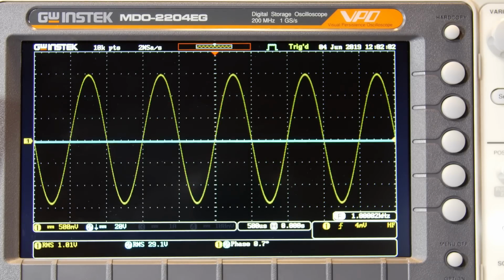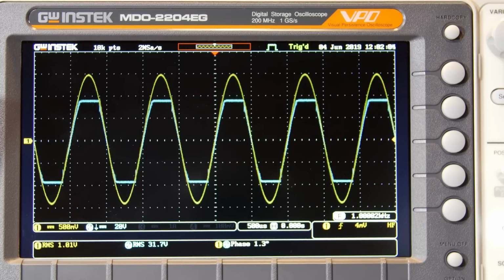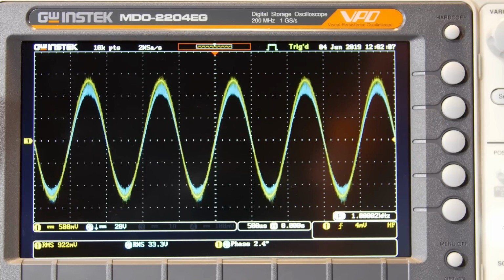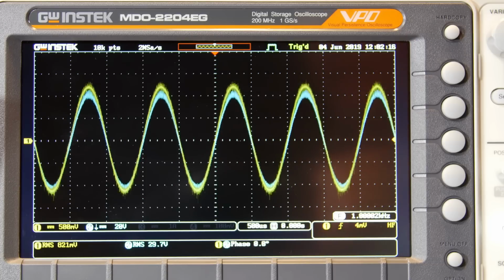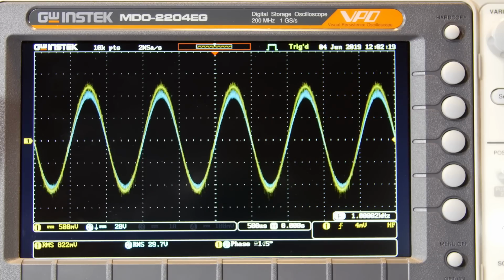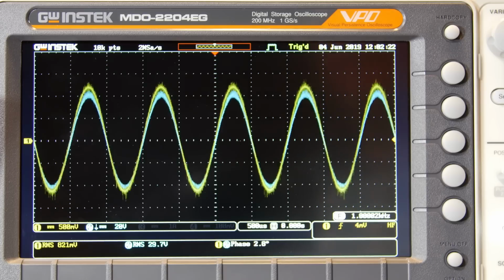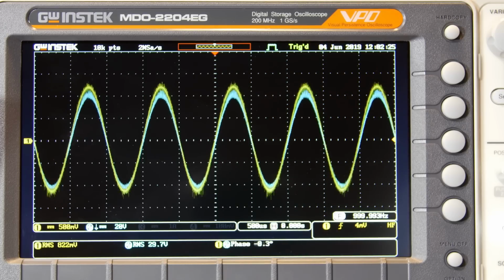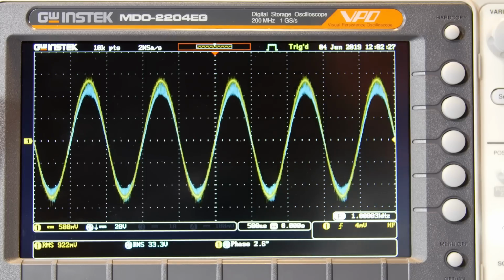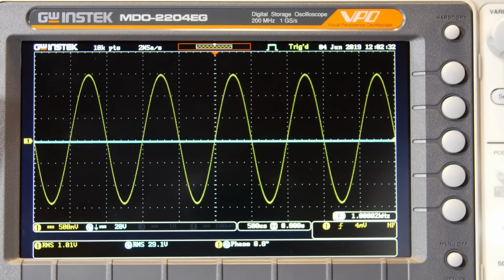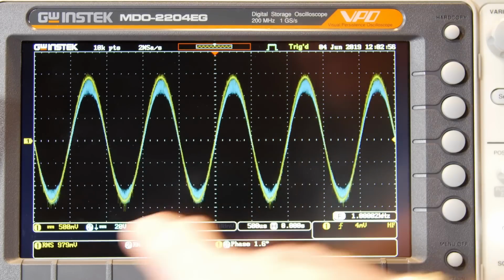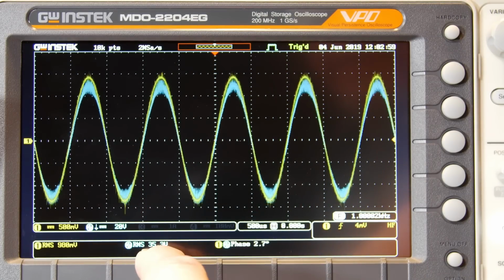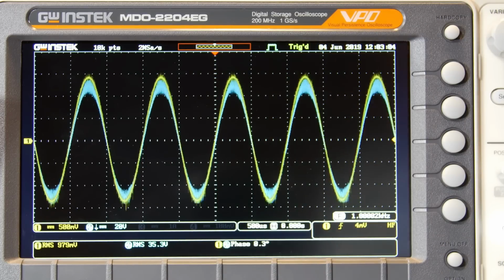Okay, we're right about 3 amps on my lab power supply. It's just tripping the current limit, so that's kind of what happens. Now we're right at 3 amps, so that's my power supply on my bench clipping, not the audio amplifier. It's about 2.6 amps. Okay, we're about 2.9 amps, and so we have about 979 millivolts in, 35 volts out, RMS, and that's about